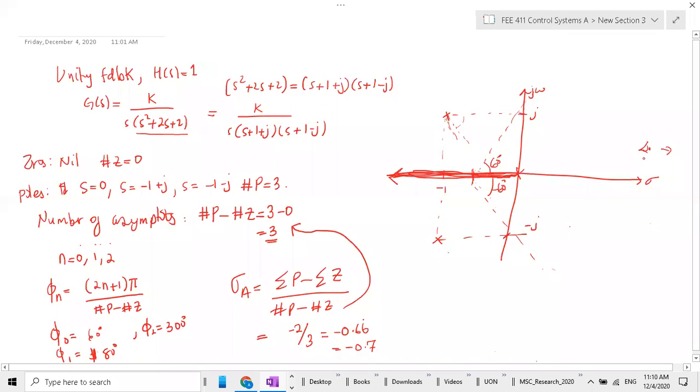According to the equation I gave you, which I didn't give you in the last notes, but in the coming notes, which I'll post maybe Monday, the angle of departure is equal to the argument of the open loop transfer function plus 180.